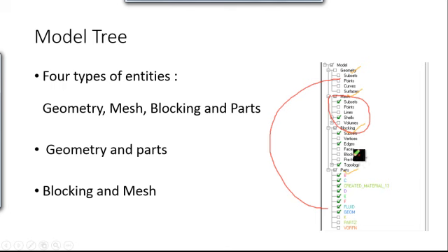For conversion from the hexa mesh to the unstructured mesh, you just need to right click on the pre-mesh and then convert. There is the option to convert to the unstructured mesh, and you will get the mesh over here. Also you can get the full hexa mesh for the typical structured solvers, like NASA is still using, or the older versions of CFX, which are based on the structured mesh.